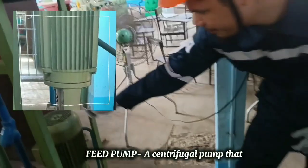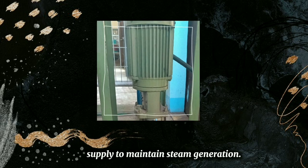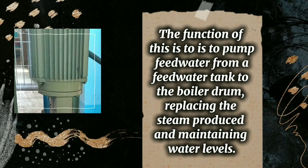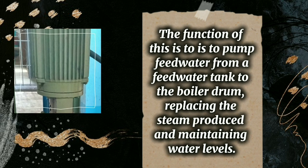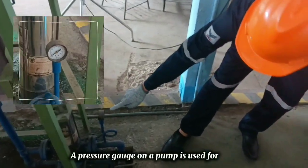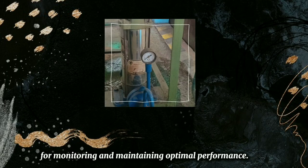Feed pump, a centrifugal pump that delivers high-pressure water to a steam boiler, ensuring a constant supply to maintain steam generation. The function of this is to pump feed water from a feed water tank to the boiler drum, replacing the steam produced and maintaining water levels. A pressure gauge on a pump is used for monitoring and maintaining optimal performance.